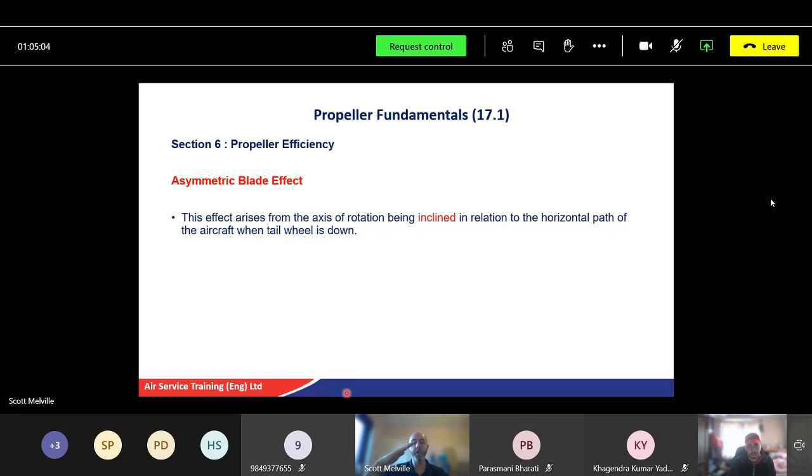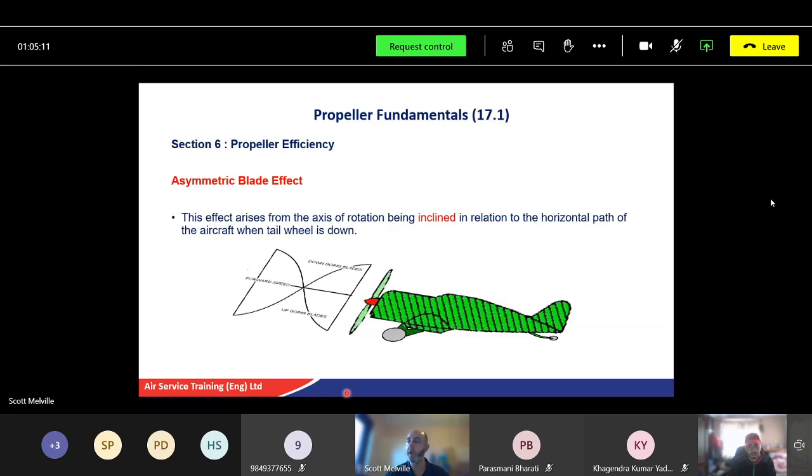So with the inclination of the propeller, that's changing the torque and reaction as it flows back away. This is what I mean here. Obviously, if this aircraft was horizontal, we'd probably have a nose wheel here, but because it's inclined, as this propeller blade comes down the way, it's closer to there, but as this blade goes up, it's further away. So that's changing the angle of attack in effect.